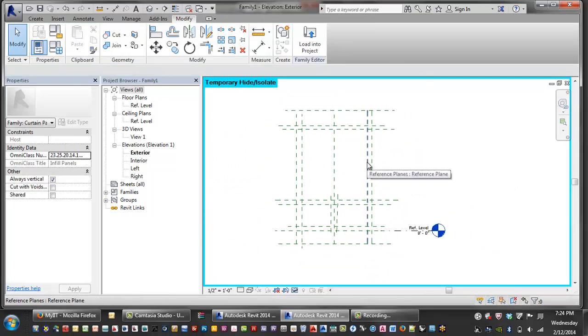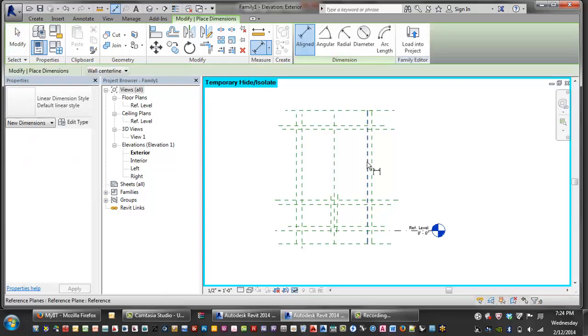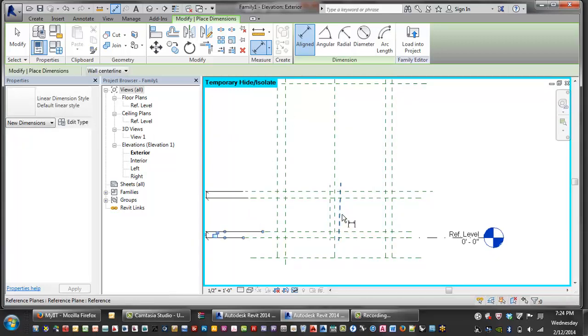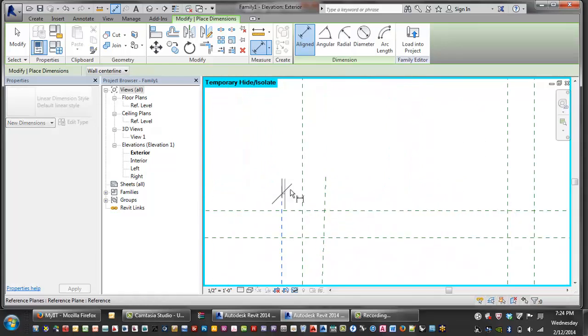So the next part is to assign parameters to each one of those. The same way I assign that offset parameter, I need to put a distance on each one of these. And I only need to do it once and only in one single view. If I do what I'm doing here in another view, it's going to over-constrain the sketch and it's not going to work. When I get to the center one, I want to make sure that I load it in with the equality constraint and then put a secondary line on that.